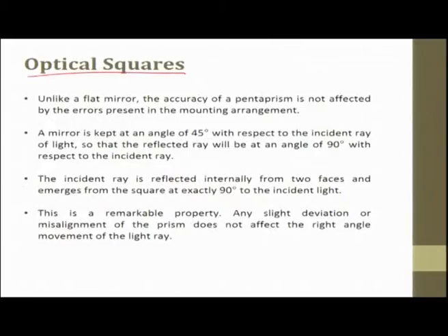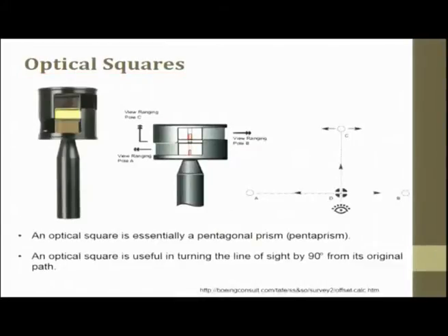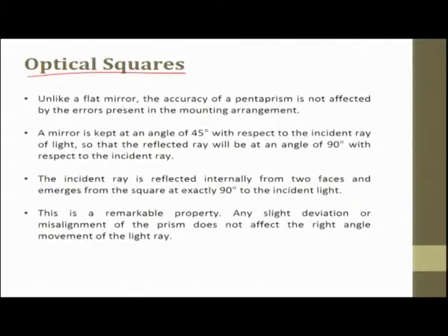Next is the optical square. Let us see the optical square. Unlike a flat mirror, the accuracy of a pentaprism is not affected by the error present in the mounting arrangement. If there is an error in the mounting, that also gets magnified when you do the measurement.